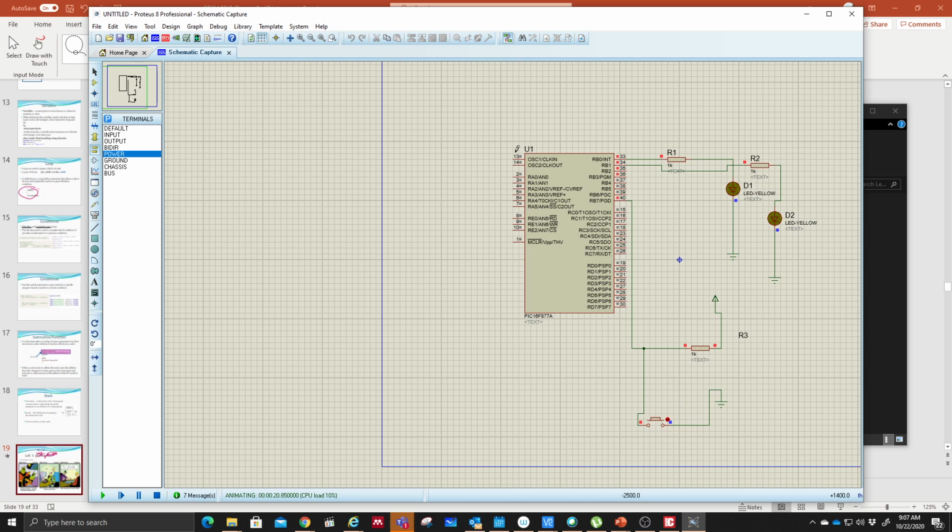This circuit can be used at this pin 1, the master clear. Remember that if you turn on this button, it's going to be a low active version because master clear is bar, so it will be active if you push your button and get a lower value over here. So this is the thing that you are going to use later.